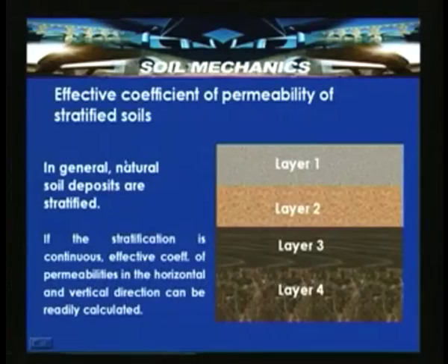So, let us look into how to arrive at the effective coefficient of permeability of stratified soils. As we said, in general natural soil deposits are highly stratified. In the beginning of these soil mechanics lectures, we have seen that soil deposits during the deposition process can have layers of soils. An example is a varved clay, which can have silt and clay deposits. So, in general natural soil deposits are all stratified.